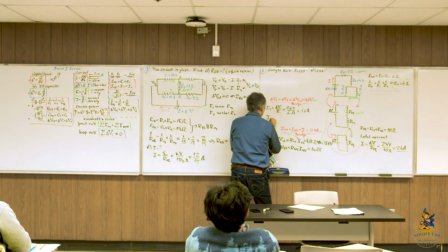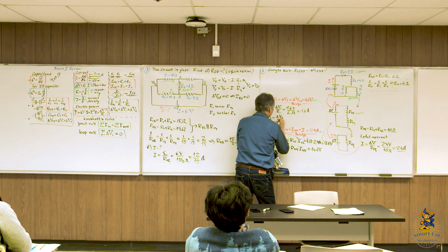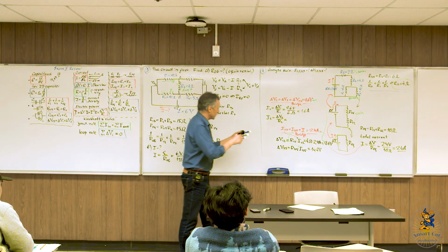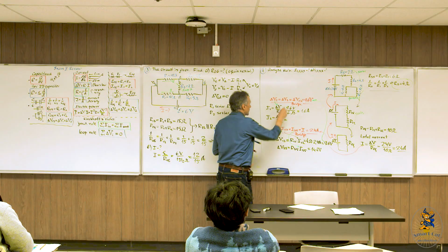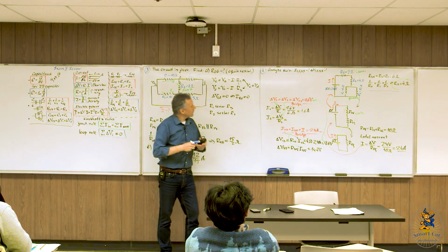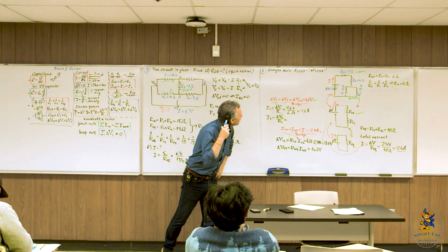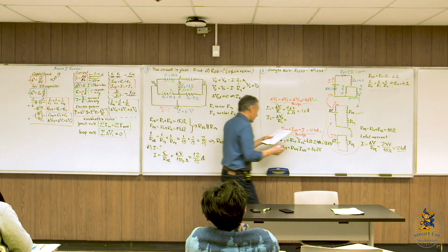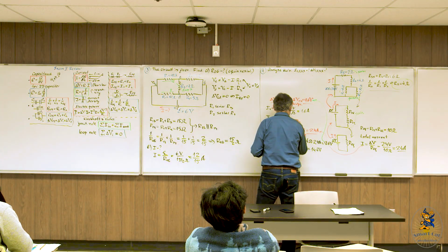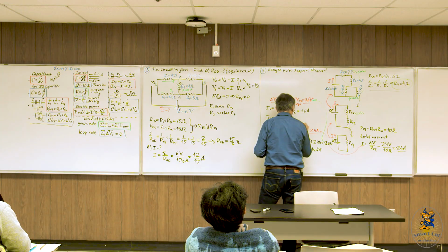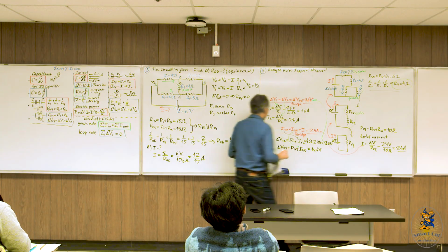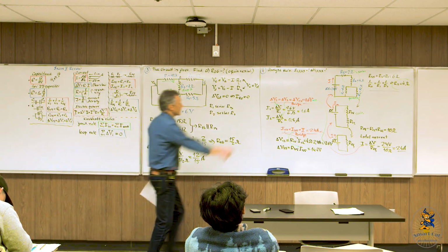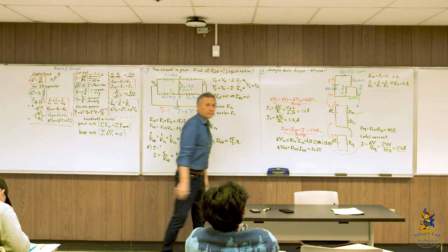And so I2 equals delta V2 divided by R2. Okay, 9.6. Again, it comes from the bridge, and this also comes from the bridge. Divided by R2 12. Let me look at my notes. So it's 0.8 amps. So we finished analyzing resistor R1 and R2. Potential differences are in the bridge. Currents we found from the bridge.